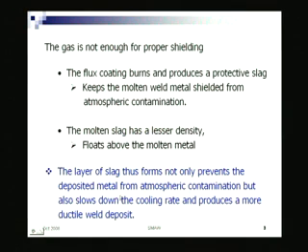So, it does that additional work of slowing down the cooling rate, because the solidified metal or weld bead is covered with a layer of slag, which is a bad conductor of heat. That leads to a reduction of the cooling rate, and we know if the cooling rate is slower, it produces a more ductile material.